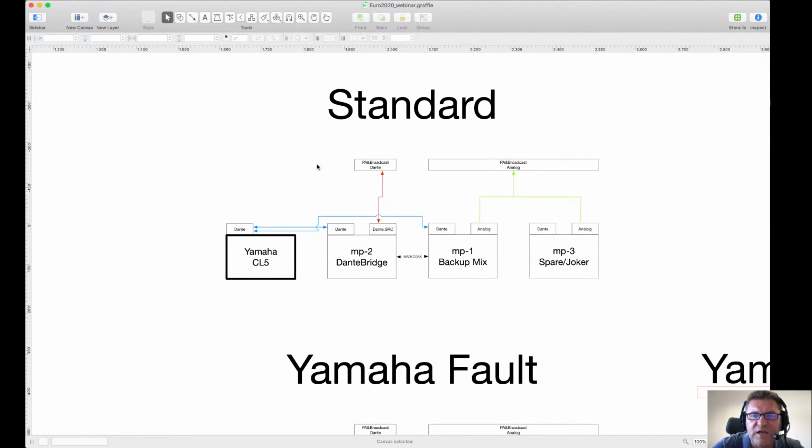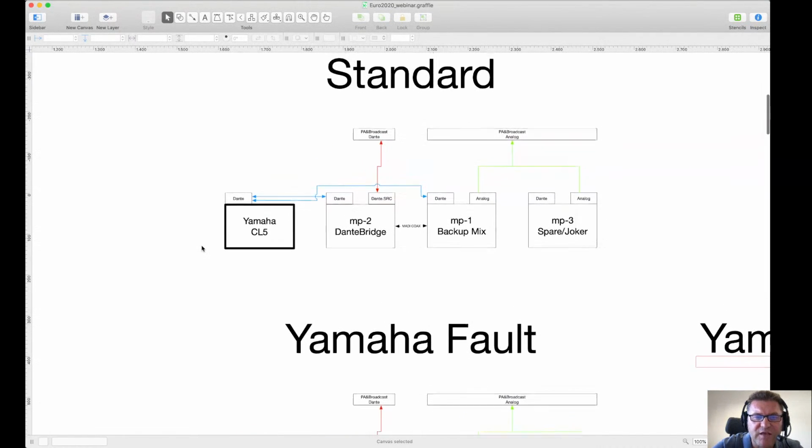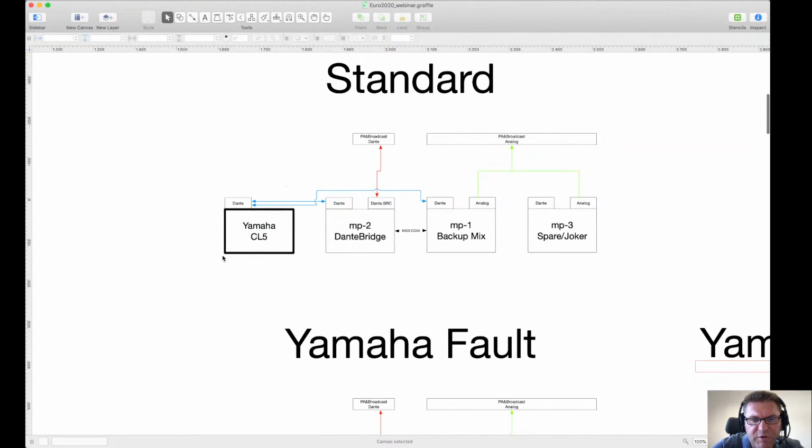Then you have to understand that usually the Yamaha consoles are extremely reliable. I don't remember a single failure of a Yamaha console in my entire career, but you have 12 minutes, anything can happen. So you need to be prepared for the catastrophe of the complete console breaking up. No panic if you have everything in place. If you have to replace the complete console, either you have an identical console and you repeat everything, or since the number of channels to be mixed was not exaggerated, we could use one of the two Prodigy.MP as a complete backup console.